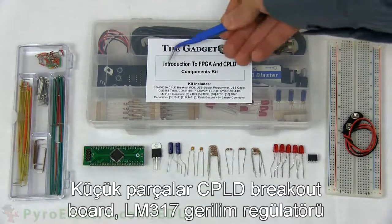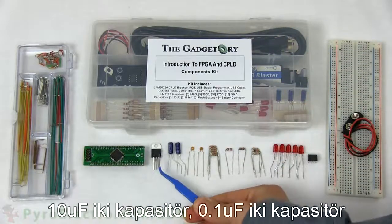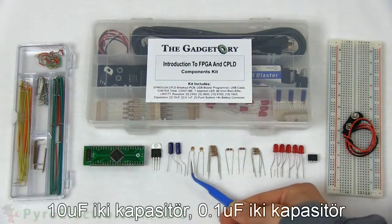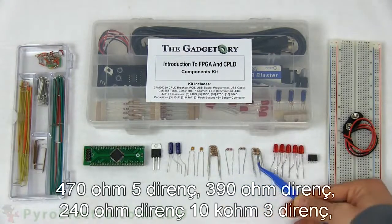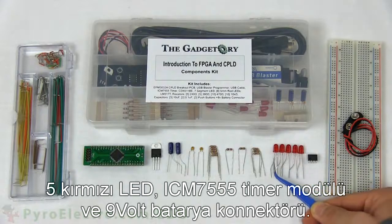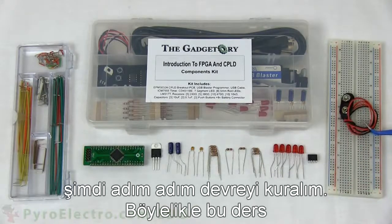The smaller parts from the components kit are a CPLD breakout board, LM317 voltage regulator, two 10 microfarad capacitors, two 0.1 microfarad capacitors, 5 470 ohm resistors, a 390 ohm resistor, a 240 ohm resistor, 3 10 kilo ohm resistors, 5 red LEDs, an ICM 7555 timer module, and a 9 volt battery connector.